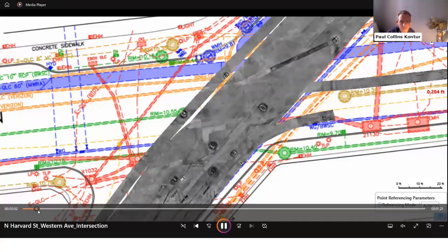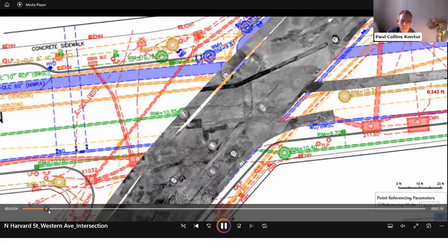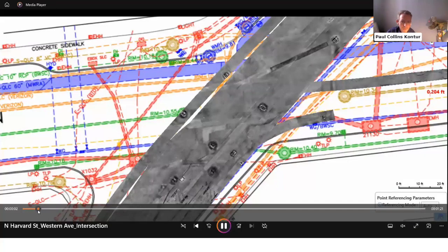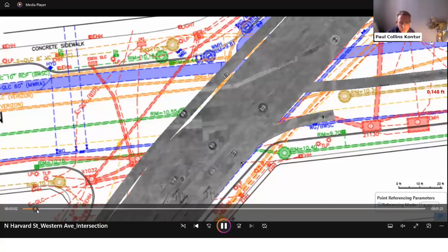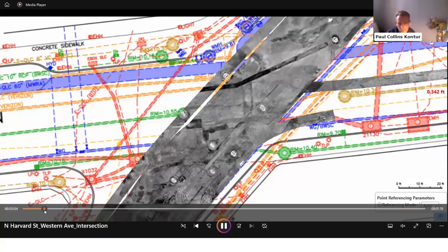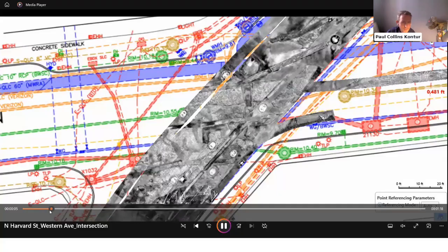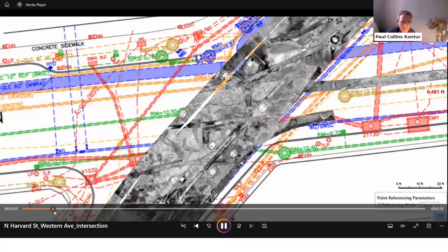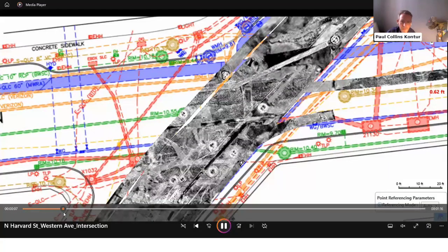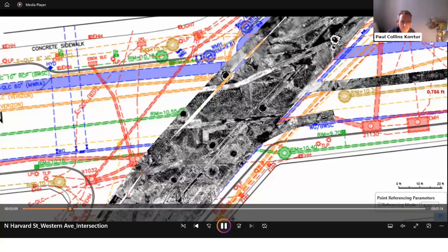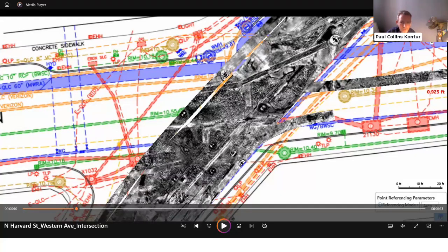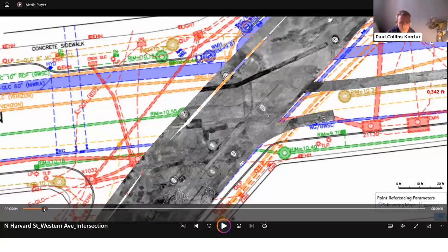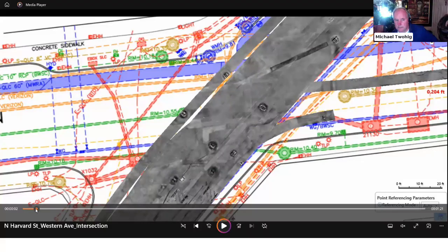And for those that haven't seen this kind of stuff before, this is, of course, like a helicopter or bird's eye view, technically called a time slice, but it's a combination of all of the channels in Mike's system, and created as an overall view of a three-dimensional system, to give us this very dense view of the subsurface, which enables us to see things like these manhole chambers, right? Obviously they're on the surface, but other things as well. People go, they pave over manholes, right? So that could be another issue, right? Yes. Where you start to see.